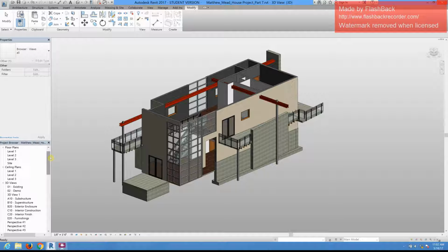All right, so let's say the assignment is going to ask you to create a working view. This is something you'll probably do forever and ever if you work in the trade. The reason you create a working view versus a view that you're going to put on your sheet is that you want a view you can get a little messy with. You can throw a bunch of lines on there and not worry about it showing up on your sheet. But then you also have a duplicate that is the finished product on your sheet, where all of that additional line work won't be shown.